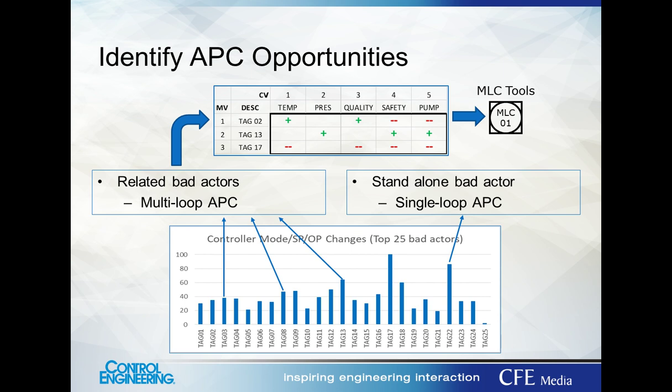Further investigation reveals the related process variables whose limits, alarms, or optimizations are triggering the frequent interventions. With variables identified, the matrix can be completed, although obviously this can be a somewhat iterative process. But it's not complicated. It all comes out of basic process operation knowledge and involving the right people, typically operations, process engineers, and control engineers.